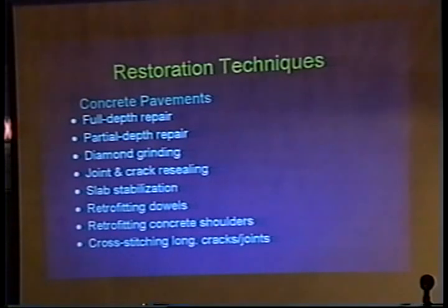I think it's 27 foot joint spacing. Reinforcing mesh was placed in there, so when it did develop a crack, hopefully that mesh would hold it together. Well, the reinforcing mesh was a little bit light, it has come under attack from the environment, and it's starting to show some movement at those cracks.